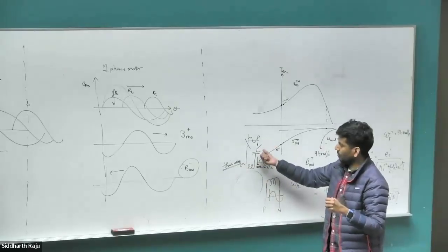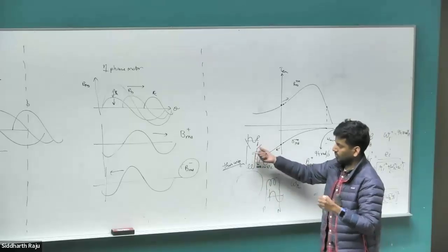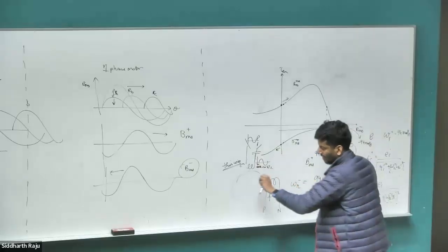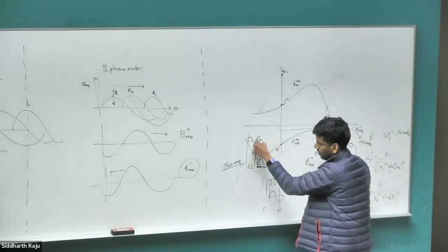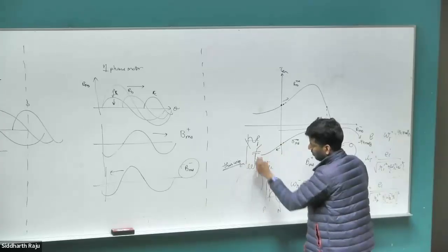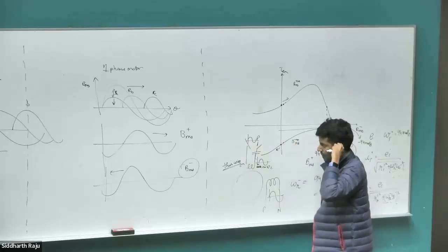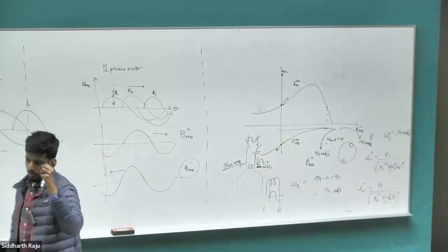The way they open the switch is somewhat ingenious. They have two mechanisms: there is a thermal switch which heats up and opens up, or there is a centrifugal switch in the case of fans. As the rotor starts to rotate, the centrifugal force will open the switch so that this coil is not utilized. If it comes to a stop, the centrifugal force will go away, so the switch will close again and excite the coil.